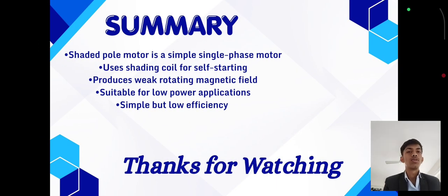Summary. So overall, the shaded pole motor is a simple single phase induction motor. It uses a shading coil for self starting and it produces a weak rotating magnetic field. It is suitable for low power applications. It is simple but low efficiency.